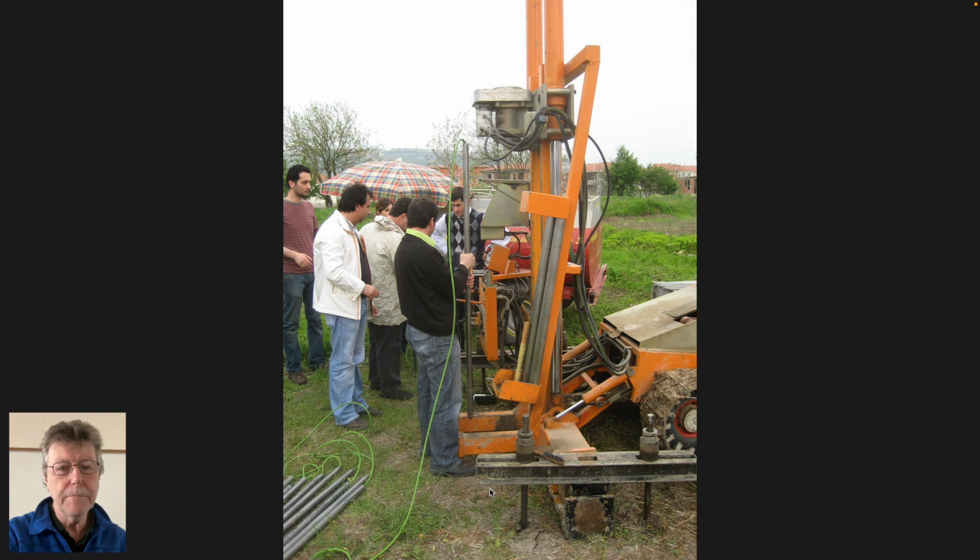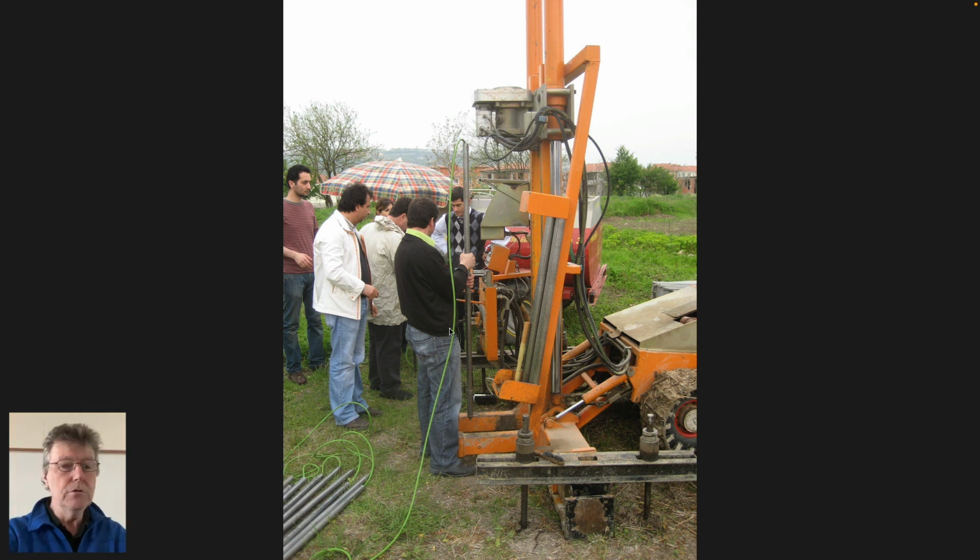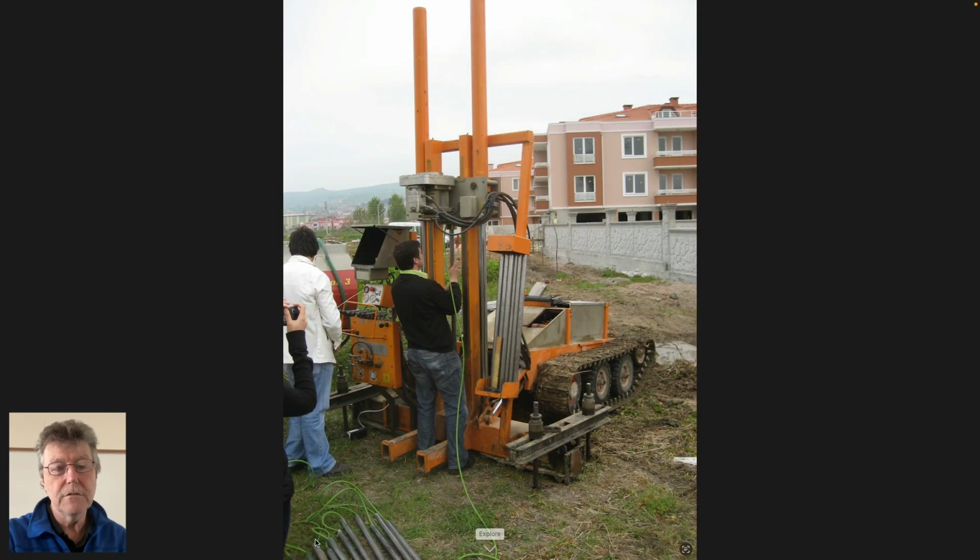We've got a longer one somewhere. Yeah, so you see it pretty well. So you stack up these rods here. You have the tip on the ground. You get it pushed into the ground by this stage going down. And once it reaches the bottom, you've already added another rod on top. It's just screwed on because you have them in this sequence here. And then that's pushed into the ground. As it's going into the ground, you add another meter. And then once it reaches the bottom of its travel, you immediately go up to the top and clamp it and continue. And so I think we've got some pictures of it doing that here.